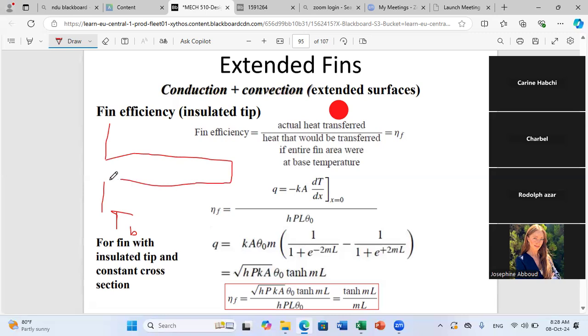If it's characterized by a very high conduction, it will allow you to propagate heat more within your fin. And as long as you have a high conduction, the temperature here will not drop a lot. So you will maintain a high temperature at the fin surface, which is good to evacuate more heat outside, because you know that convection is proportional to T at x minus T infinity. Okay, actually through your fin the temperature will drop.